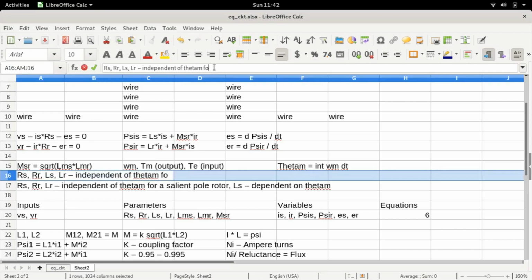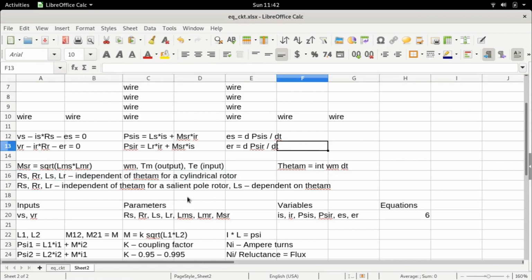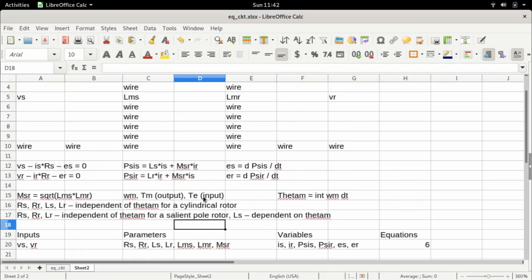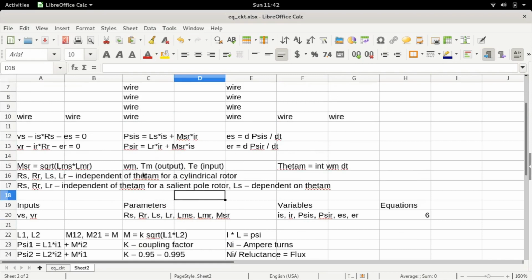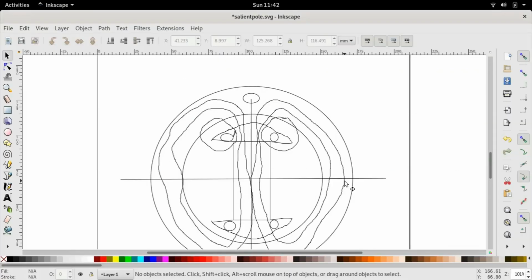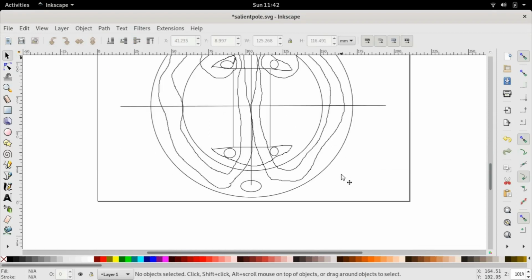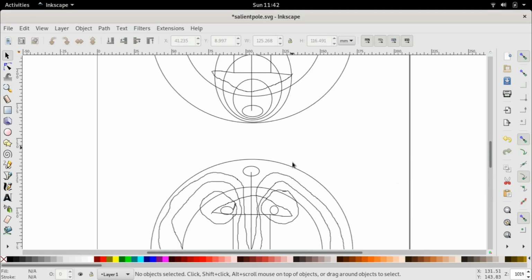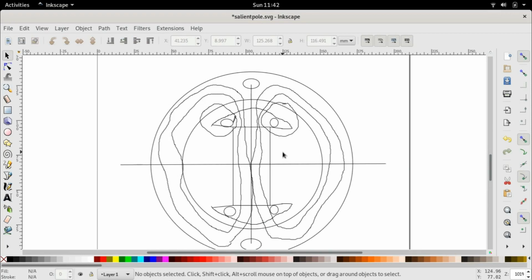So this case is for a cylindrical rotor, which is the case of a squirrel cage induction motor. Right? The salient pole rotor is a special construction which is found, but it is not going to be talked about in the beginning because it's an advanced case. So this is worth looking at, because when you come to understanding how motors work and behave, in trying to build a mathematical model, these flux lines play a huge role. This is why I always say that when you're trying to understand how a machine behaves, try to draw these flux lines and figure this part out, because this is the real understanding of a machine rather than just writing equations.